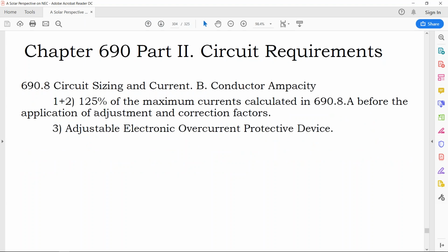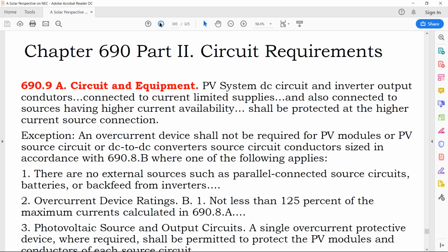And then you adjust for temperature correction. That's if the array is not governed by voltage regulators or controllers that can throttle the power output, like microinverters or SolarEdge optimizers. At that point, it is just a 25% upsizing.